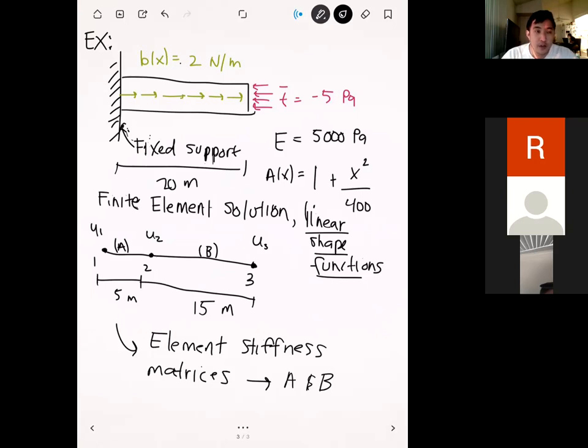If you imagine a simple beam that we load like this, the stresses are actually going to be highest right next to the fixed support, because that's where you go from something that's 0 to some displacement right there. So in reality, there is a lot of motivation to have a finer mesh next to your fixed supports, because that's where the most interesting stresses are going to occur. That wasn't the motivation for this problem, but it just happened to be like that. But in reality, that's one consideration for sure.